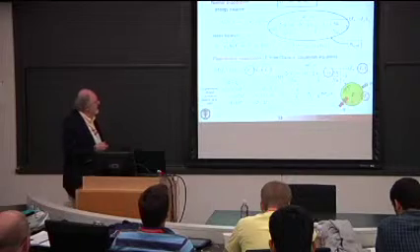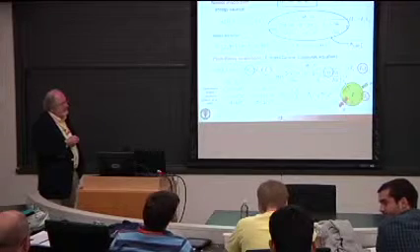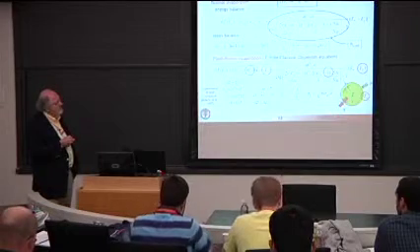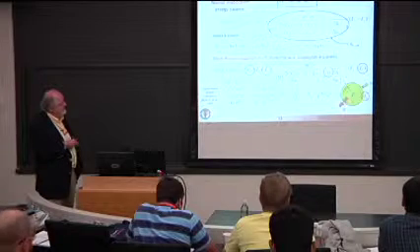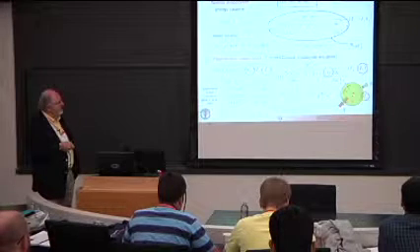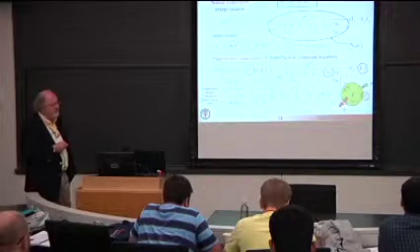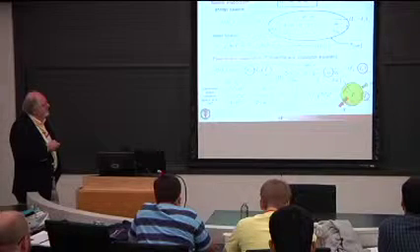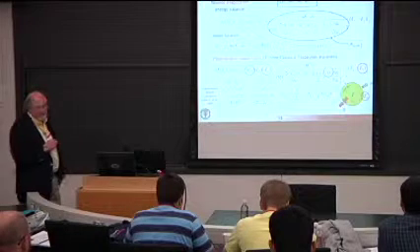So a busy slide here, but basically, if we just look at the surface boundary condition, we have the mass transfer rate, or the droplet vaporization rate, m dot here, times the latent heat, which depends on the surface temperature of the droplet. And that's going to be balanced by the heat coming from the internals of the drop, due to the drop temperature being higher than the surface temperature, and from heat transferred from the exterior to the surface of the drop. So if you look at this equation and look first at the first term on the left-hand side, the driving force is the difference between the drop temperature and the surface temperature.